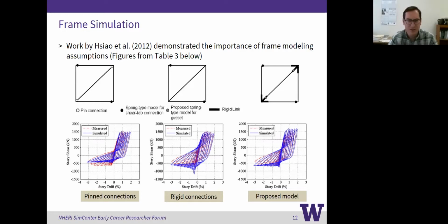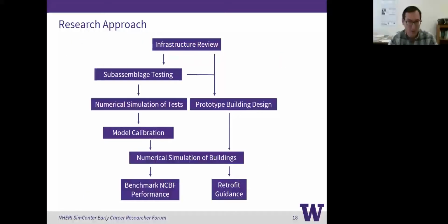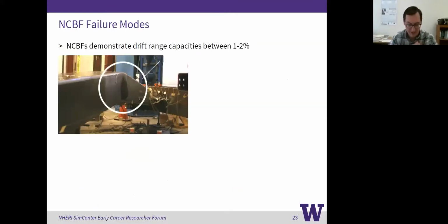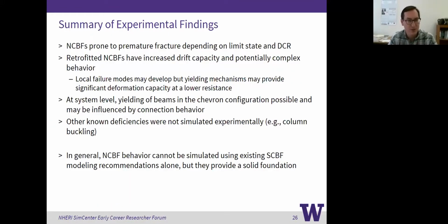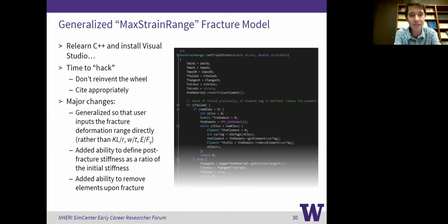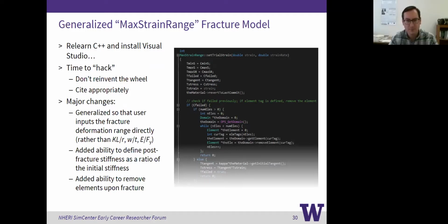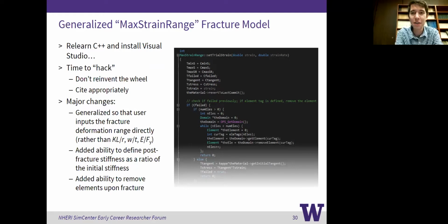Okay. And then some questions about the element removal command. Maybe one question is around the recorders associated with those elements. Does the element remove command take out recorders or handle the recorders at all? It's a good question. So I haven't actually made recorders for those elements that I've been removing. But I believe because the element no longer exists in the domain, the recorder will just go blank and not record anything. But I have to say I haven't tested that case.